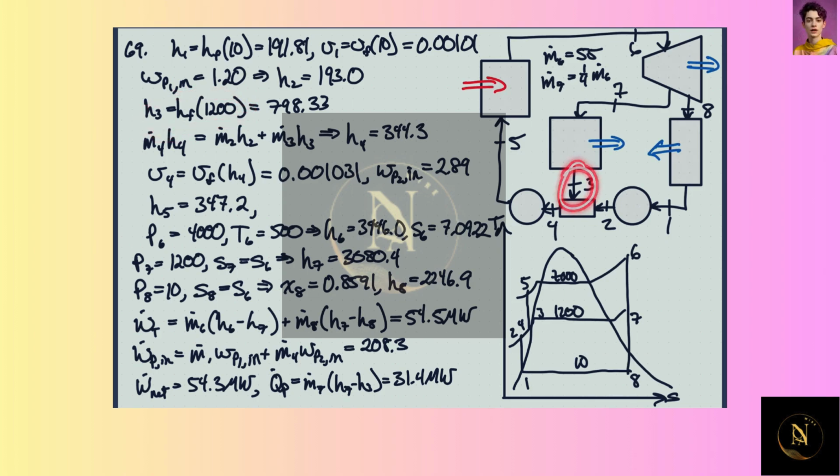again, we're assuming that state 3 is a saturated liquid. And so we have the enthalpy for a saturated liquid at 1.2 megapascals, it's this value. So that's at 3. Now, if we look at the mixing chamber here, do a control volume around it and an energy balance on it, we have the enthalpy flowing out and the enthalpy flowing in, and they must be equal. And so now we see we have H3, we have H4, no, we have H2 and H3.